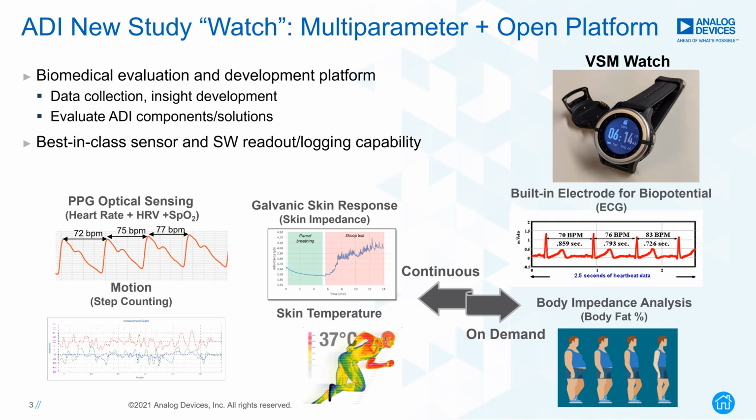Just to give you an example of a temperature sensor here, it's the ADT7422. It is fairly accurate, up to 0.1 degree C in the band of, let's say, 25 C to 50 degree C. And even if you take the wider temperature range from -20 to 105, the typical industrial temperature range, this sensor would still give you 0.25 degree C of accuracy. This is just one example.